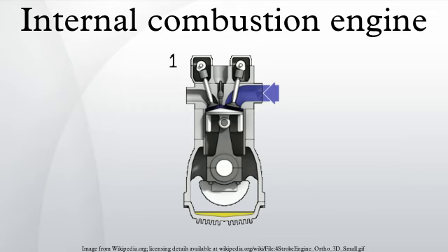6-stroke engine. The 6-stroke engine was invented in 1883. Four kinds of 6-stroke use a regular piston in a regular cylinder, firing every 3 crankshaft revolutions. The systems capture the wasted heat of the 4-stroke Otto cycle with an injection of air or water. The Beare head and piston charger engines operate as opposed piston engines, 2 pistons in a single cylinder, firing every 2 revolutions, more like a regular 4-stroke.